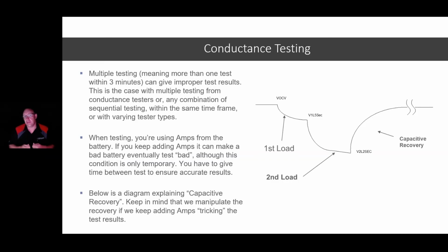Okay. And number 3, don't test and then charge and then test and then charge and then test. You're going to have a different result every time if you do that. So the point with conductance testing is that we want to test the battery in its normal state of operation, not its shop state of operation, its normal state, how the customer uses that car. They drive the car, they pull into their garage, they park, they leave it there for a half hour, they leave it there overnight, whatever it is, right?